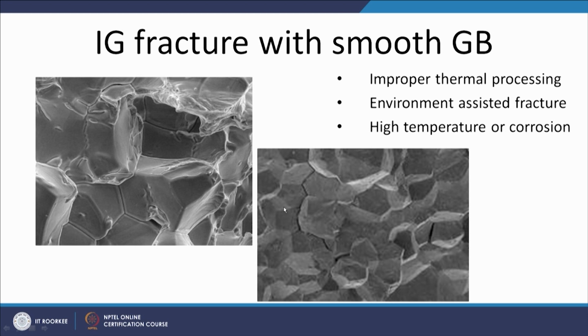Now, as I have said, when the grain boundary area is poor in terms of limited slip deformation systems, or the presence of weak phases, or some specific elements like oxygen in Inconel and iron and antimony in the case of copper, these constituents weaken the grain boundary areas.